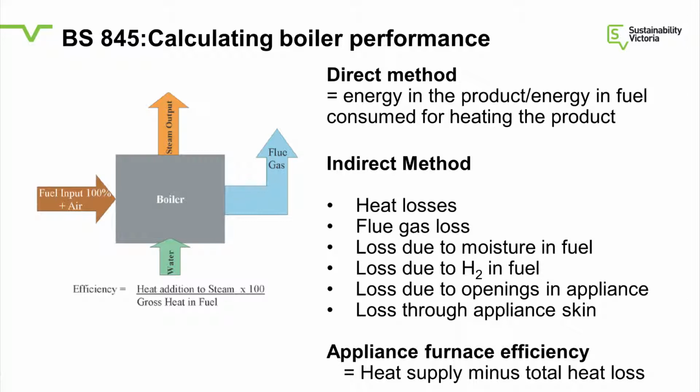Fairly simple, really. If you look at the sketch, you've fundamentally got fuel going into the boiler. That energy's got to go somewhere. It either goes into the steam or hot water, or it'll flow into the flue gases, or through the radiation losses from the casing of the boiler. So that's really what you're trying to measure.